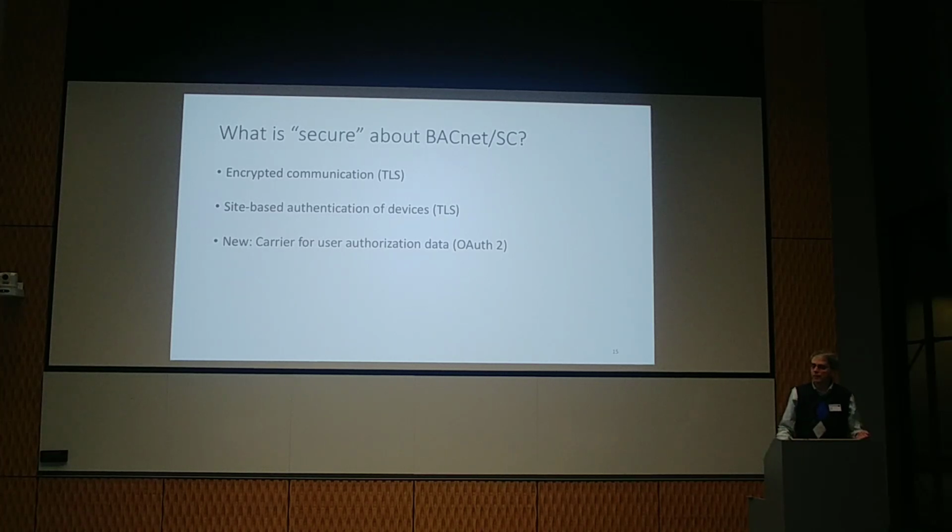So what does this mean? Let's say you're BU and you have vendors putting devices on networks that you control. Right now, if I had physical access to the MSTP network in this building, I could hook up an MSTP device and start talking back into all the other Siemens controllers in this building. With BACnet SC, that won't be possible unless the building owner wants to run a really lax network.